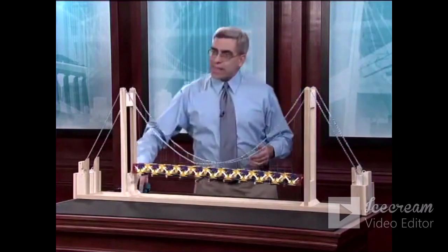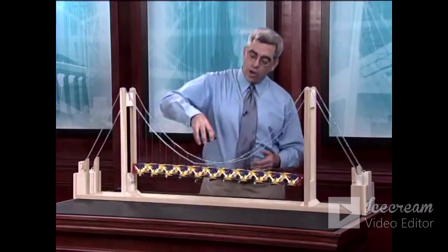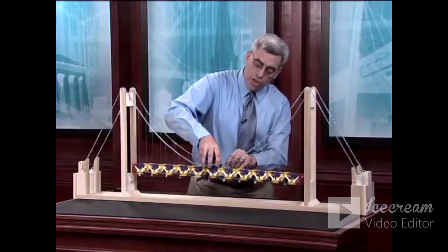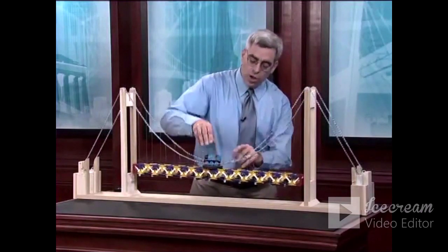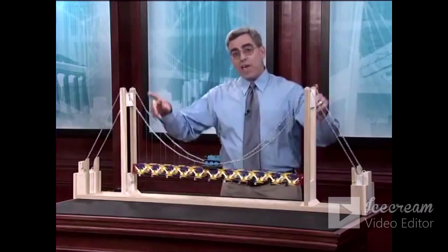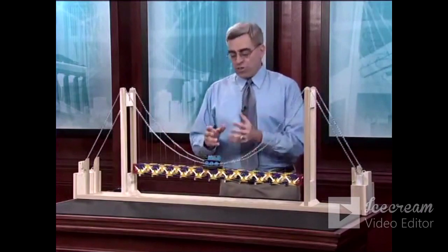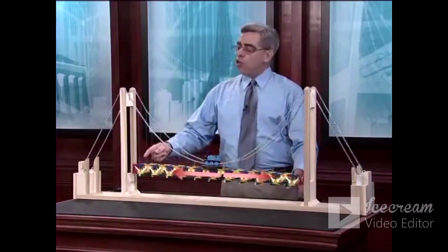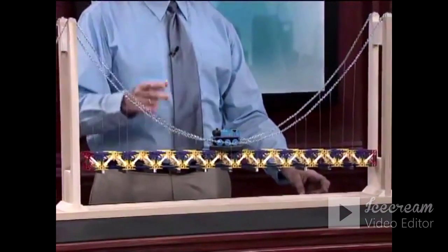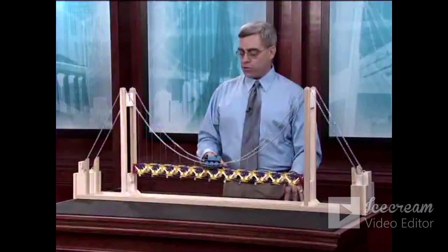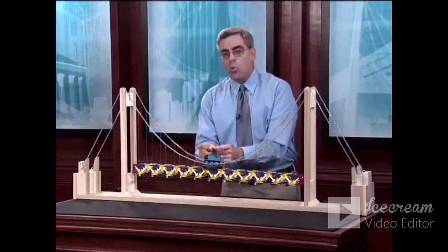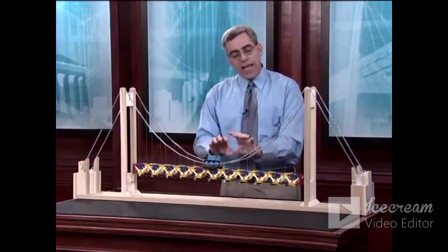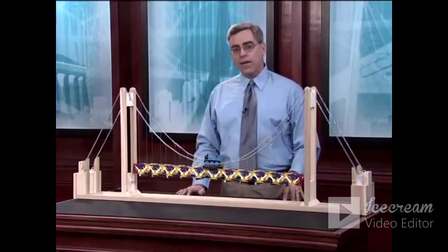But now when I take this same heavy concentrated load of the vehicle crossing the bridge and we place it on the stiffening truss, we see that the shape of the cables didn't change at all. What the stiffening truss does is to distribute that heavy load out laterally so that all of these slender vertical wires, they're called suspenders, carry that load instead of just 1 or 2 suspenders, as you saw in the case of the unstiffened deck.